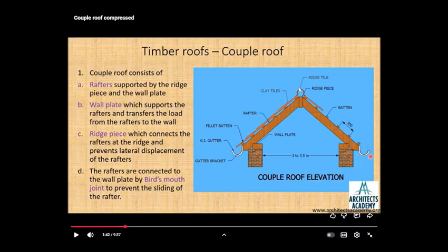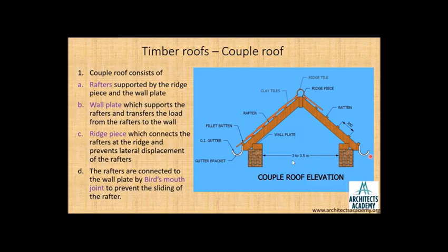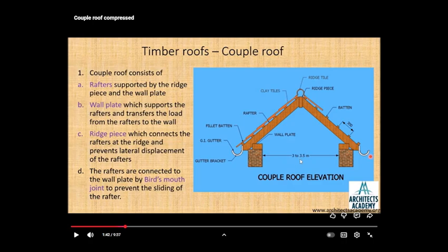top of the roof, the rafters will spread, and the only thing holding it up is the walls. So the walls have to stop it from spreading. That's why it says span from 3 to 3.5 meters. There's nothing they can do to make that span bigger, because unless you've got really massive buttress walls, it's going to be putting big forces on the walls.